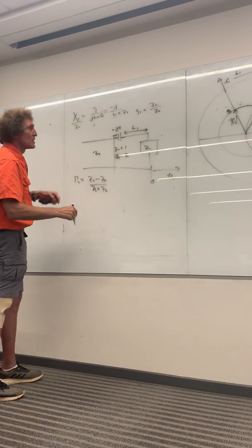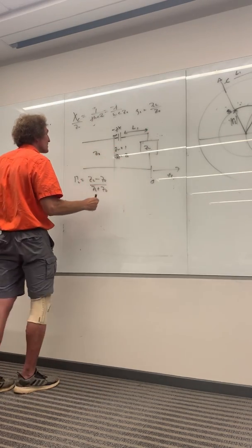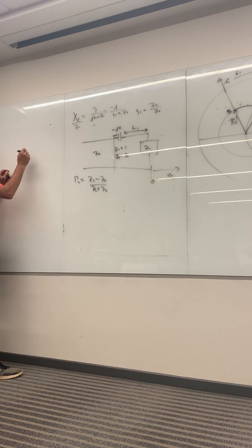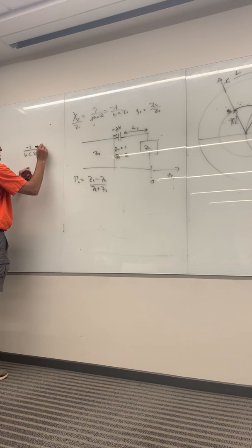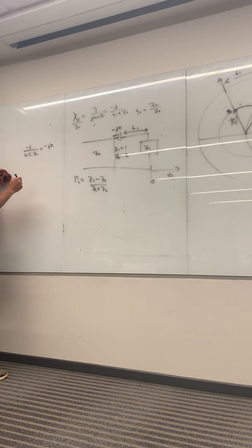And then we would say, whatever this value of jX is there, I would say that the capacitive reactance, which is 1 over j omega C, well, minus j over omega C times Z naught, would be equal to the actual minus jX that I needed, which means that the value of C would be equal to 1 over omega Z naught X. Do you follow me on this, class? Are you with me? And that would do it.